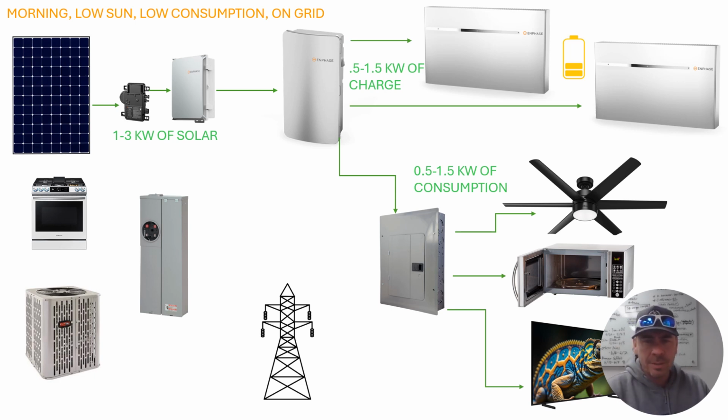Let's say perhaps you have a battery system that can't do what I'm about to show you. That would be an incompatibility issue, where the batteries aren't capable of having the solar function on its own without grid presence. That happens with the Tesla Powerwall 2 and some older string inverters and older microinverters that may be installed on an older system where you're trying to upgrade and put a new battery on it. Not everything's compatible with the Tesla battery systems, the Enphase systems, or the SunVault power systems, so there are some caveats. But what I'm showing you is a walkthrough for compatible systems.